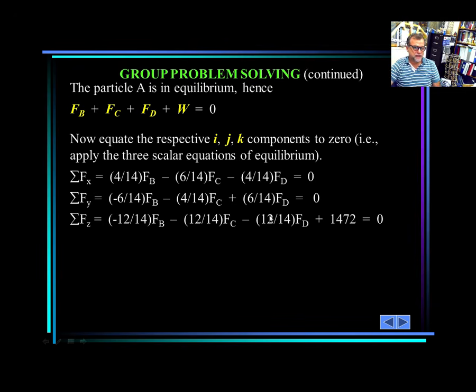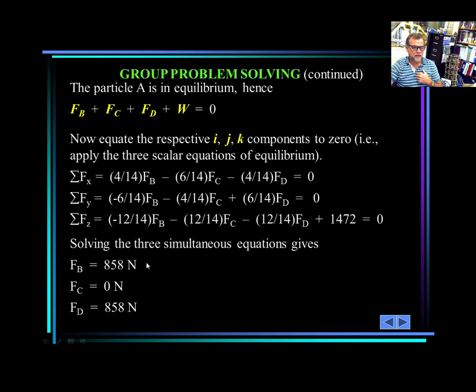So basically, this is the component of the weight, because it's going only in the z direction. But the important thing with this problem is that you solve the system and you find these results. Every single time I see that, when you find those results, everybody starts second guessing themselves. And it's good. Second guessing yourself is good, not only that, but interpreting your results. That's the good part. That means that the tension in this cable is 0.